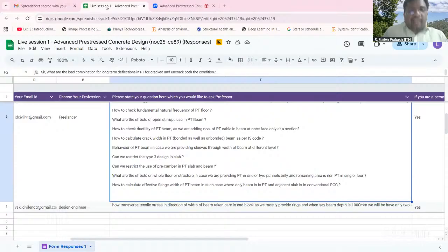So you're right, we have to put it at locations where the bending moments are zero or close to the point of inflection, but we need clear guidelines on that. In fact, this has created a lot of issues. It has led to deflections and cracking in the beam, and then we have to go for structural strengthening.